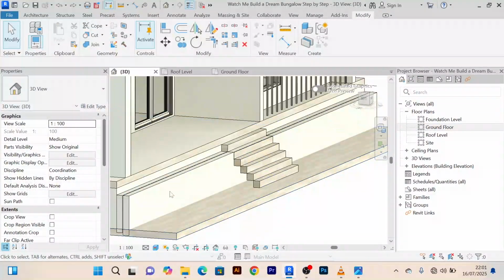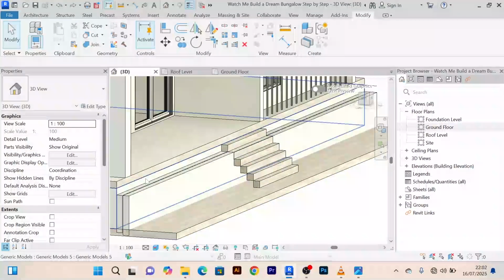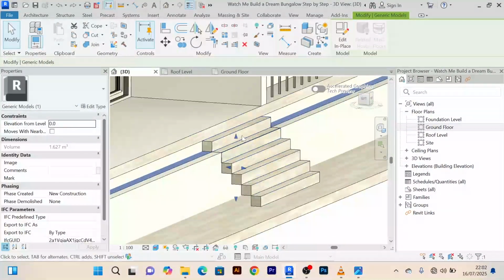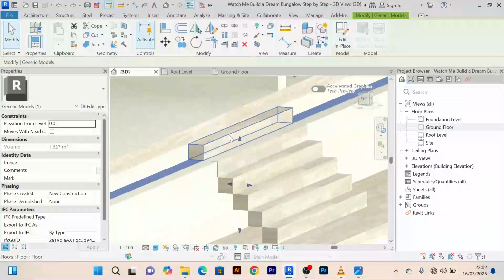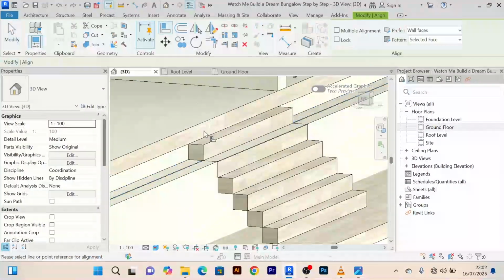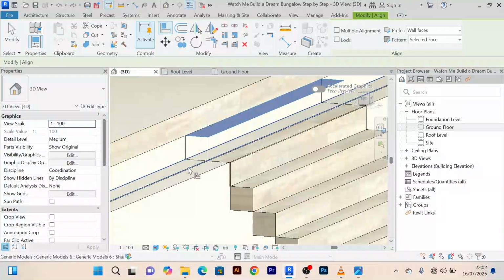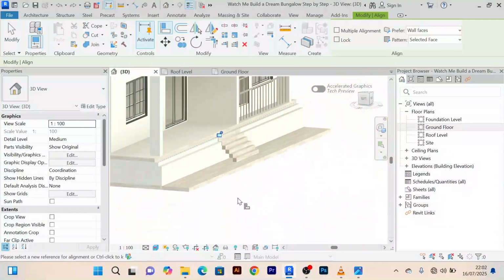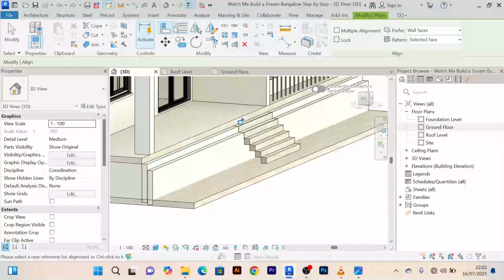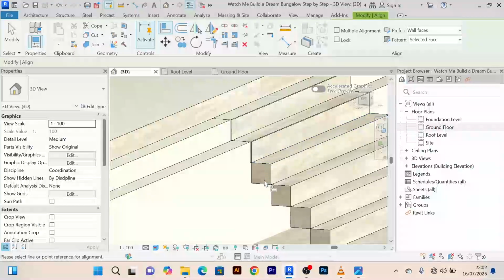What I realized is that these extrusions are not supposed to extend all the way to this other side. In fact, let me first drag this one up. Let me even link it up with this part like that. But then it has to just stop around here.